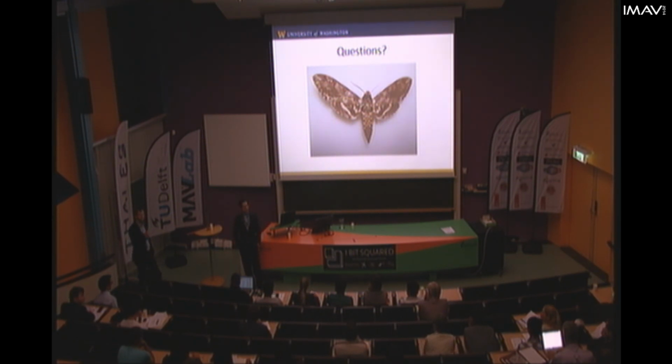Are there more questions? Yes? If I understood correctly, the mechanics is based on a linear bending model. You're taking into account the bending stiffness of the structure, but not the stretching. Correct. Now this is a membrane, and membranes are primarily dominated by in-plane stresses. Stretching. So how good is this model considering this geometry?